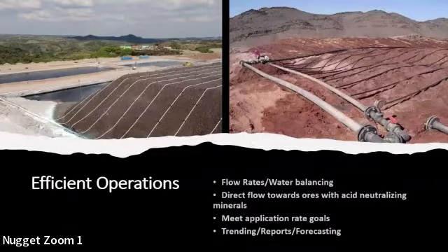The clay speciation. So what we identified here, again from the XRD analysis, is that both the SP and the argillic ores had very little smectite. Smectite is a swelling type clay. We see 2% or less for those ores. However, in the advanced argillic, we do see upwards of 8% smectite type clay in one of those samples and 4% in another. So there are swelling type clays in here. So not only is it a finer textured ore, but it also has swelling type clays associated with it.